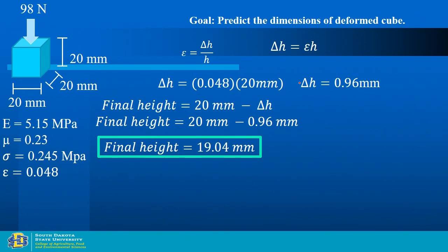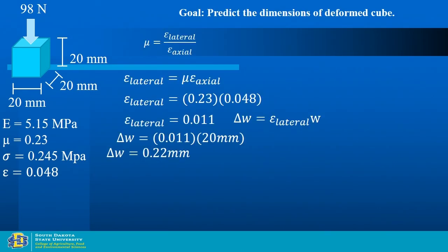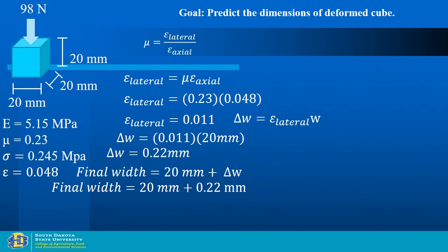The question here is only about delta W. She can understand delta H, that's good. So when you have a decrease in height, delta H change, the width in the other two directions increases. When it decreases, these two widths will be increased because of the same volume, right? Not the same volume, but there are more spaces, so that can be accounted for when you do the actual compression. So the increase in width will be 0.22 according to the calculations, in both directions. Other questions?